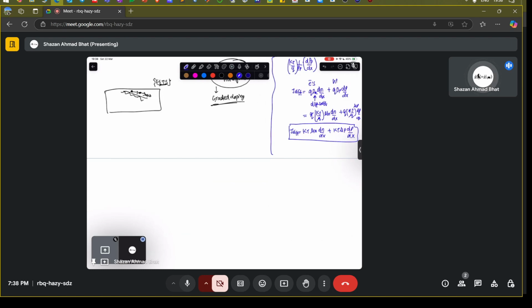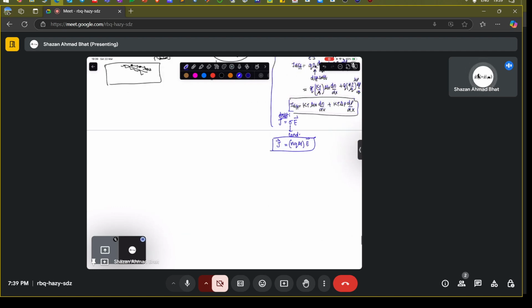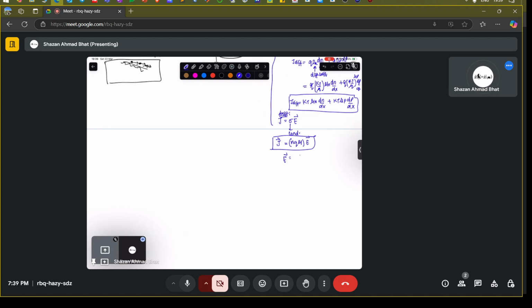You know from microscopic Ohm's law, the drift current is sigma times the electric field E. This is the conductivity, and you can write conductivity as N Q mu. That means you can write the electric field as drift current divided by N Q mu.